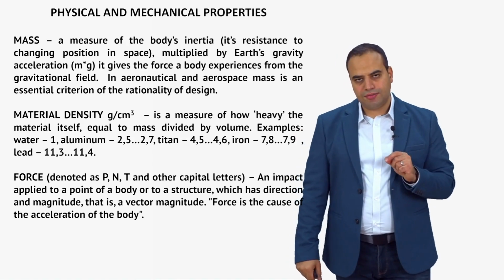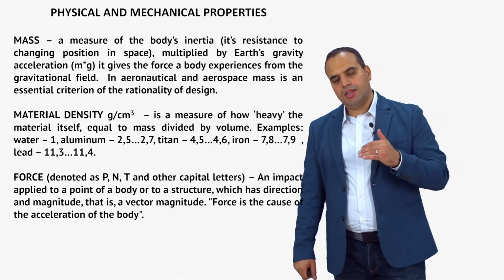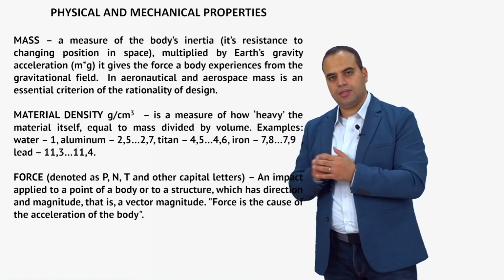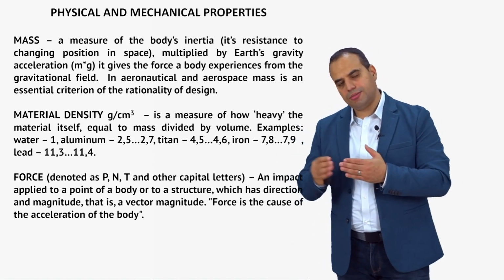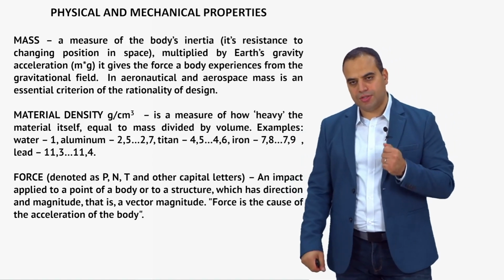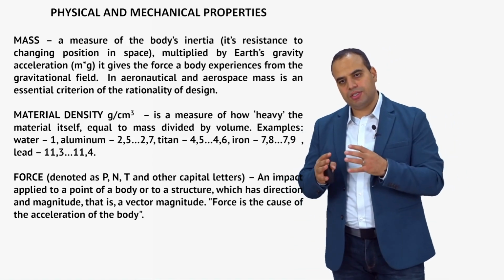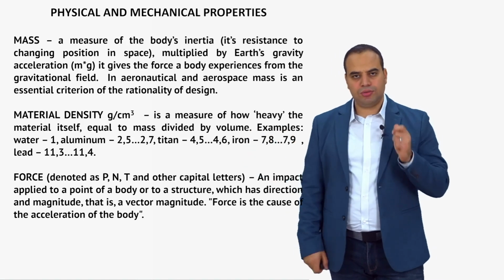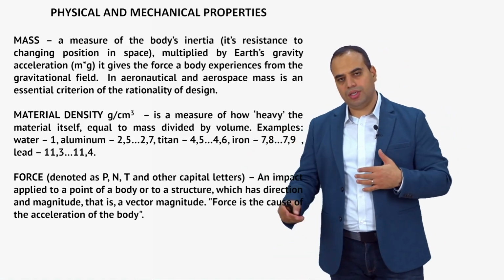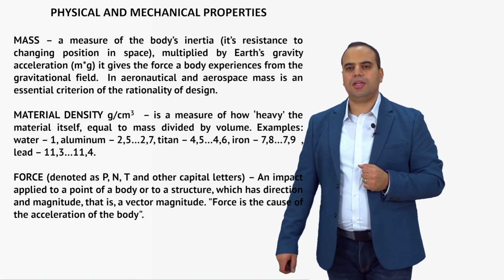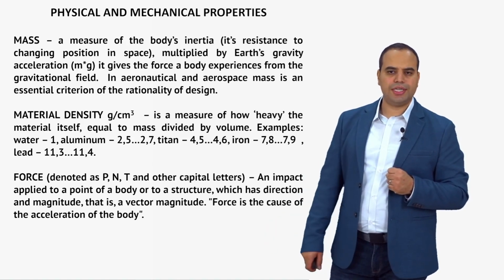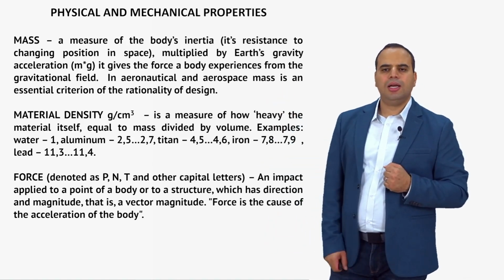Usually, it is not the density itself that is important, but the ratio of the density to its strength, right? Because every material has a different strength and also a different stiffness level, right? So the strength and the stiffness divided by the density is going to say whether the material is good or whether it is too heavy, for example, for designing an airframe structure that is going to be good in terms of taking the loads and in terms of the mass.